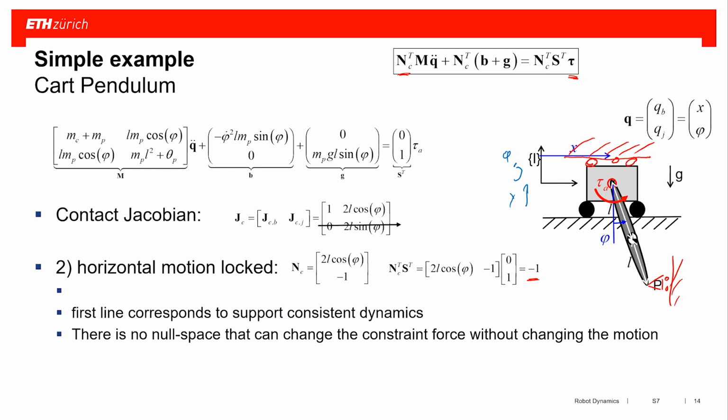And the last question here again is, do we need to restrict the acceleration of the contact point? Whenever we are talking about dynamics, we're talking about acceleration. So any constraint, any formulation of a task, of an objective, how we would like to move, has to be somehow propagated to acceleration level.